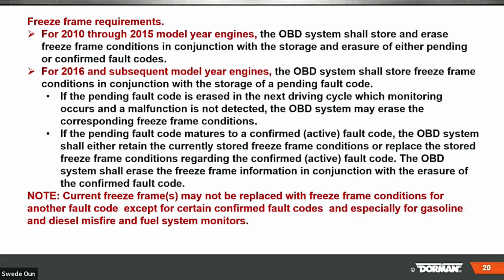Not to mention, once you repair that vehicle, you know this particular fault happened when I was doing 40 miles an hour, when the temperature was this, when the load was this. And if you truly want to make sure that you fix that vehicle, duplicate that condition. Let the computer put it out and you can't go wrong.